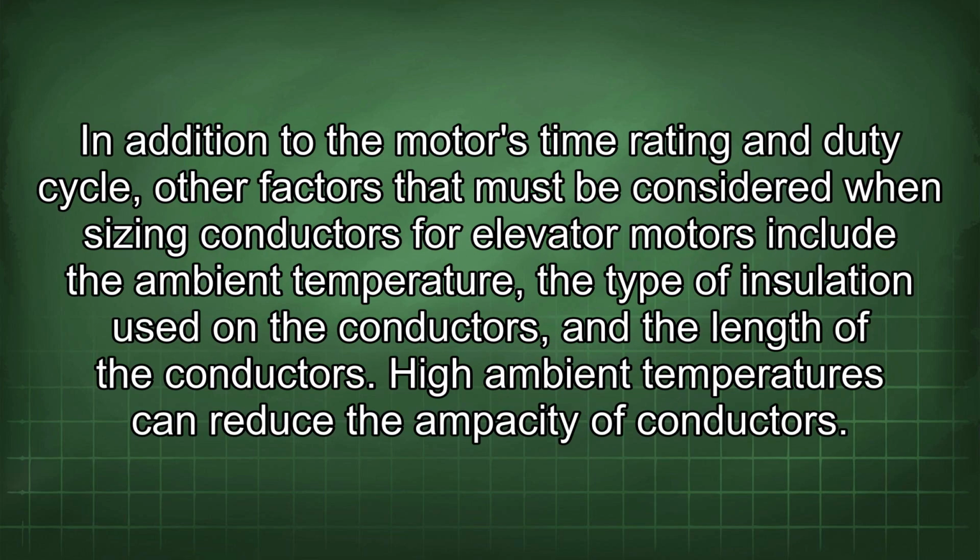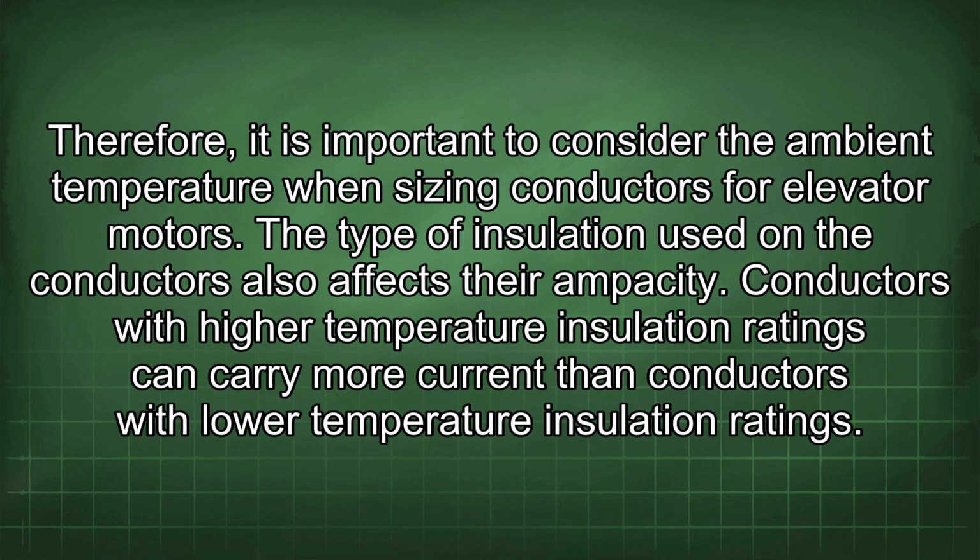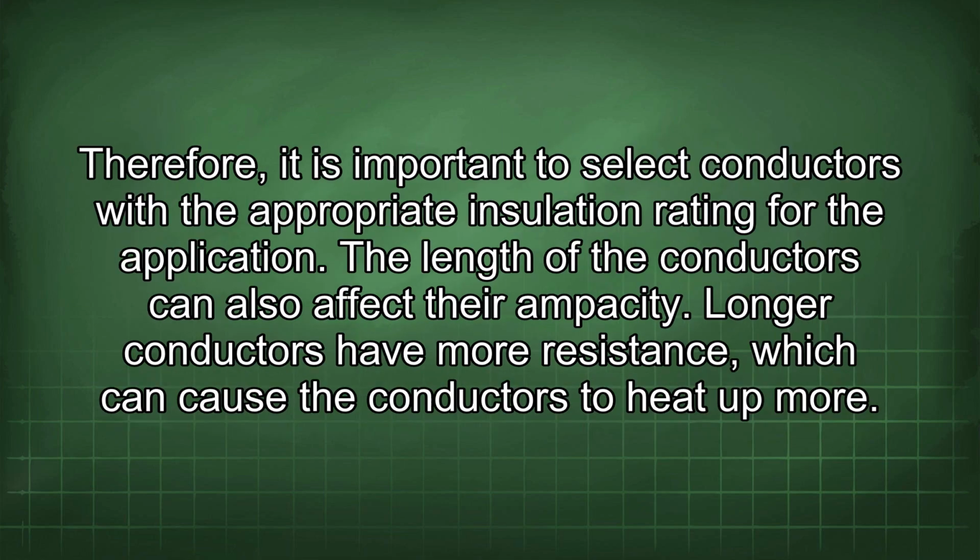conductors. In addition to the motor's time rating and duty cycle, other factors that must be considered when sizing conductors for elevator motors include the ambient temperature, the type of insulation used on the conductors, and the length of the conductors. High ambient temperatures can reduce the ampacity of conductors. Therefore, it is important to consider the ambient temperature when sizing conductors for elevator motors. The type of insulation used on the conductors also affects their ampacity. Conductors with higher temperature insulation ratings can carry more current than conductors with lower temperature insulation ratings. Therefore, it is important to select conductors with the appropriate insulation rating for the application.